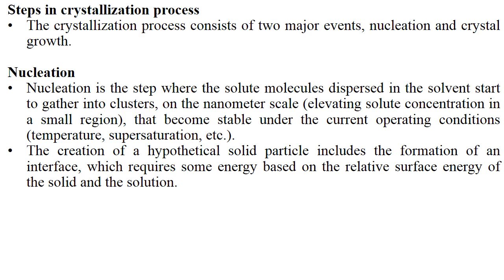Because when the solute molecules are gathering at a specific point on a nanoscale, that point becomes more concentrated, because the molecules of the solute are concentrating there. That becomes stable under the current operating conditions, temperature or supersaturation, etc. The creation of a hypothetical solid particle includes the formation of an interface, which requires some energy based on the relative surface energy of the solid and the solution. If this energy is not available and no suitable nucleation surface is available, supersaturation occurs.